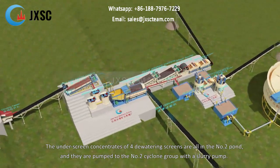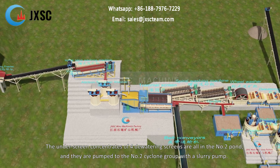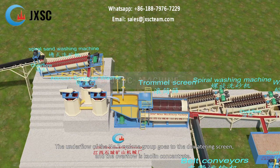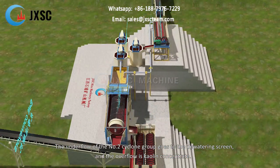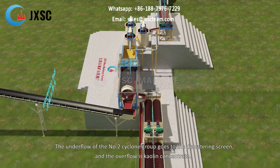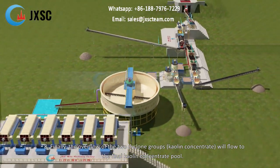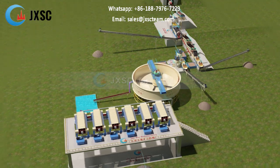The underscreen concentrates of 4 dewatering screens are all in the number 2 pond, and they are pumped to the number 2 cyclone group with a slurry pump. The underflow of the number 2 cyclone group goes to the dewatering screen, and the overflow is kaolin concentrate. 8. Finally, the overflow of the 2 cyclone groups, kaolin concentrate, will flow to the final kaolin concentrate pool.